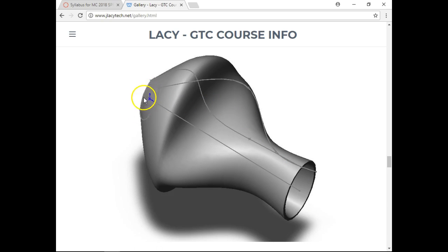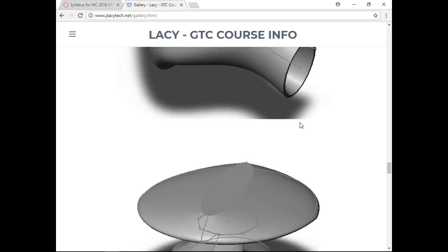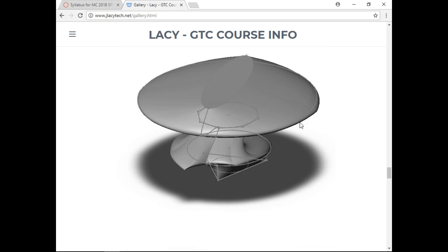curves. So basically the ellipse going through the path with guide curves determining how it bulges and which way it bulges. And then the same thing with a loft. We have a triangle going to a circle to the octagon, back to an ellipse, and the guide curve kind of determines how it bulges and which way it goes.